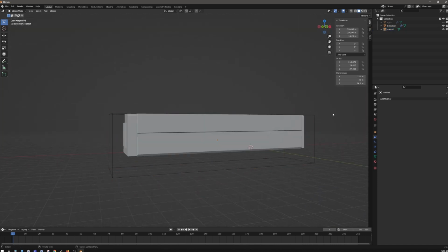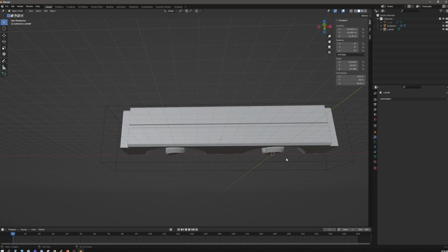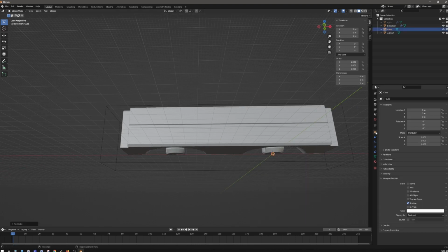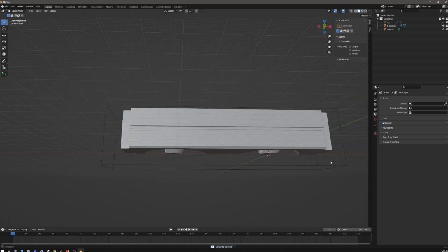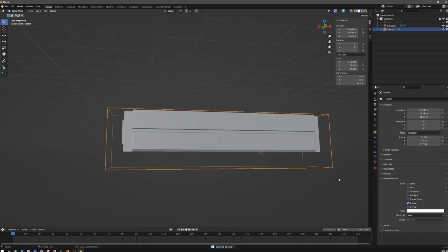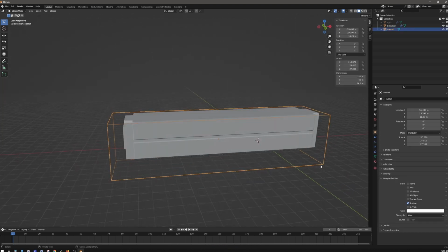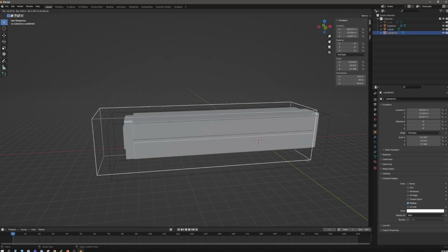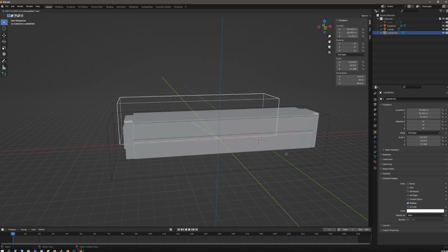So what do we do? Let's go ahead. We can do one of two things. We can hit Shift A, make a new box, okay, and then set its parameters to wired, so we know it's a cutting object, or we can just go ahead and take an object we've already set up parameters for, which is this, and Shift D, and then we can move this wherever we want, okay?